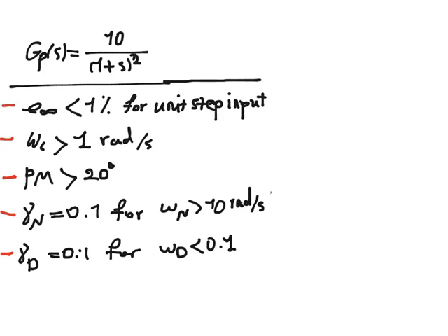We only needed to increase the amplitude for low frequencies in order to have a better performance in terms of the steady state error, and also to satisfy the attenuation of the disturbance. Now in this video we are going to design a PI controller.